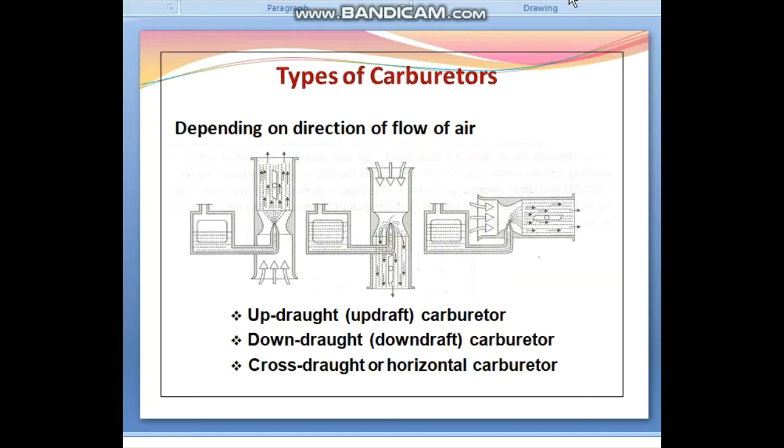The disadvantage of the updraft carburetor is that it must lift the sprayed fuel droplets by air friction. Hence, it must be designed with a relatively small mixing tube and throat, so that even at low engine speed, the air velocity is sufficient to lift and carry the fuel particles along.